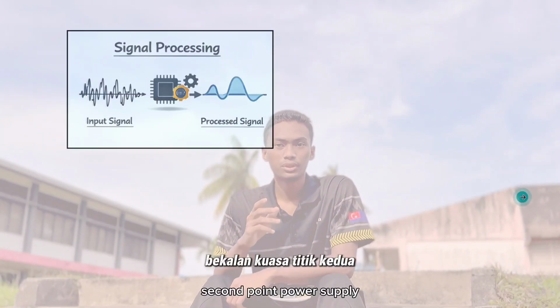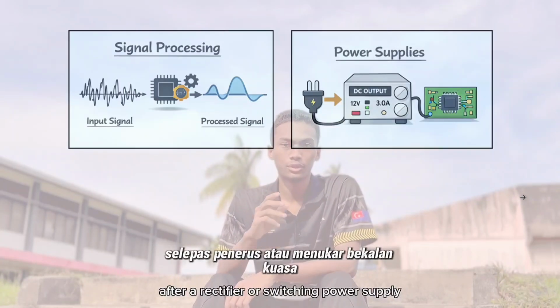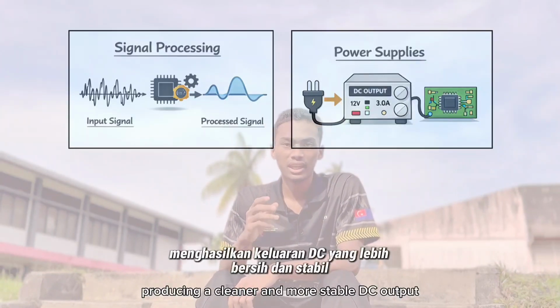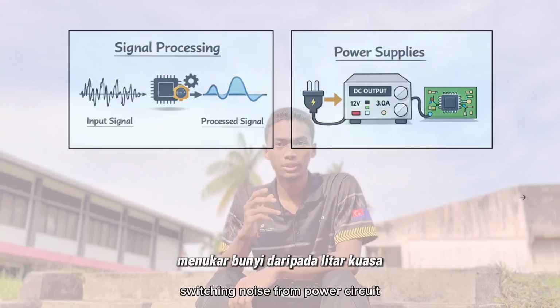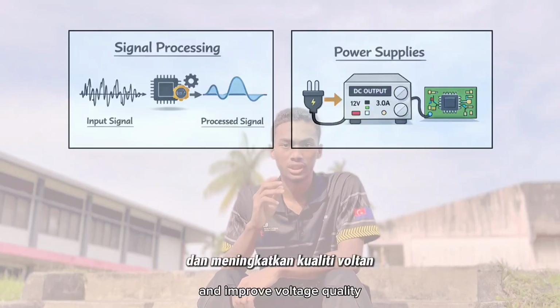Second point, power supply. In power electronics, low pass filters are used after a rectifier or switching power supply to remove high frequency ripple and noise, producing a cleaner and more stable DC output. The function is to filter switching noise from power circuits, provide stable DC for sensitive equipment and improve voltage quality.